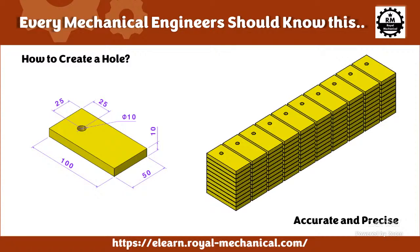The other thing is, each and every hole which we make within that component should be accurate and precise. Accurate in terms of the dimensions. For example, look at the rectangular plate we have: if we say the diameter of the hole should be 10 mm, and it should be positioned at a distance of 25 mm from the edges, then it has to be accurate. And it has to be precise in the sense that when I'm making hundreds of such parts, the variation should not be too much. It has to be quite precise as per the design requirement.